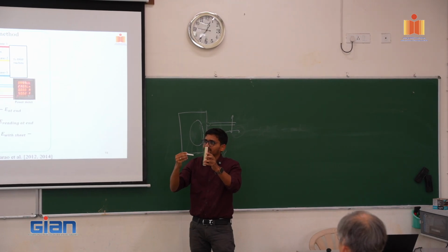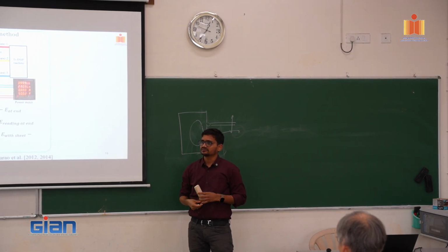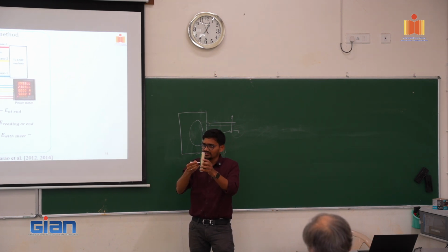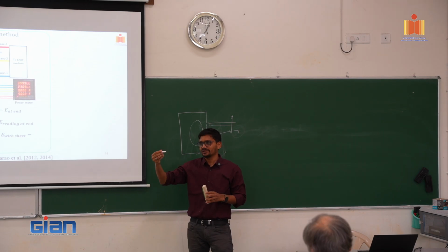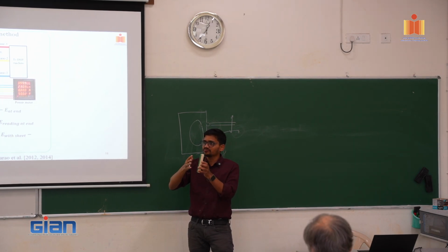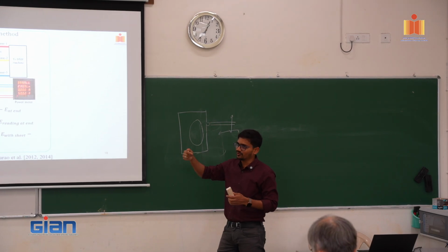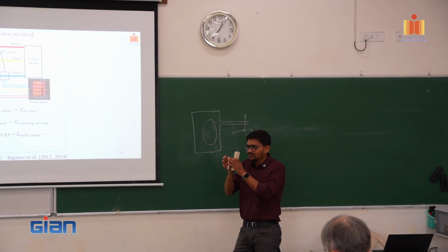So the depth of free traverse and the depth with the sheet is the same. When the plastic deformation is happening, it is not independent of the tool motion. So experimentally, while you are measuring that, you cannot differentiate them directly.